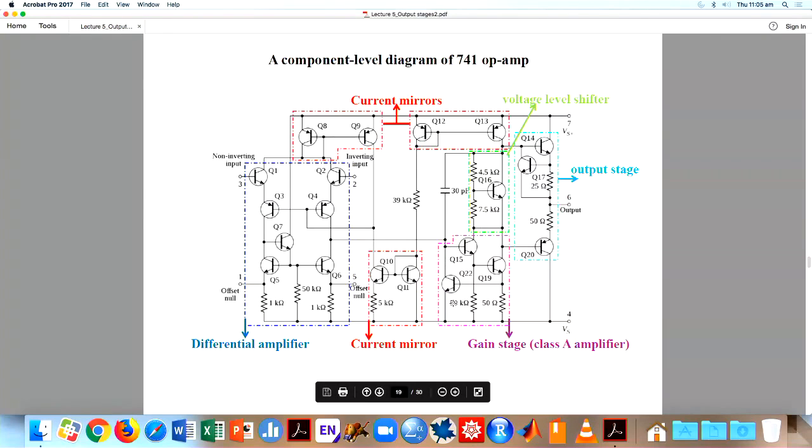If you are using a single transistor amplifier, you don't have the effect of differential. A differential amplifier can cancel out noise. That property is not there. You can't make an ultra low noise amplifier. Then if you are using a transistor amplifier, you can't get lots of amplification because an operational amplifier has multiple stages.